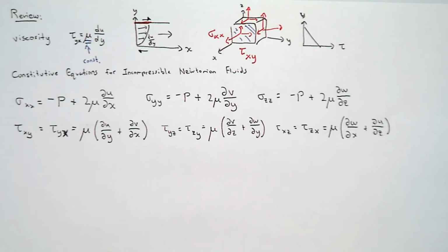And that's why I mentioned it's a little bit easier when you take a strength of materials class, because those professors actually explain it better than I do. Whatever shear stress you apply in this direction, you have to apply an equivalent shear stress in this direction. You have to. If you don't, then you're going to have relative deformation that essentially changes your volume, and then it wouldn't be an incompressible fluid.